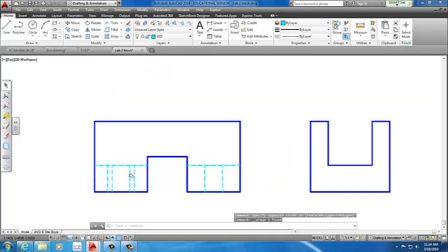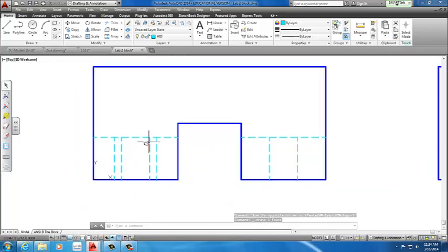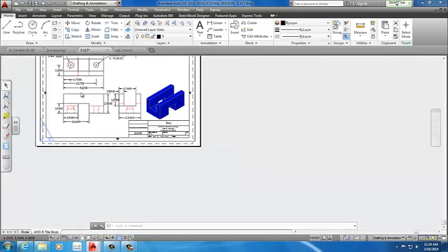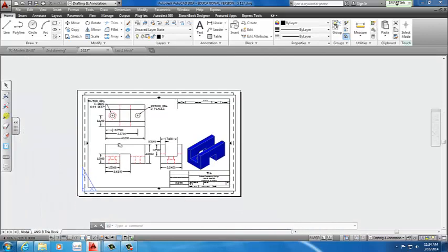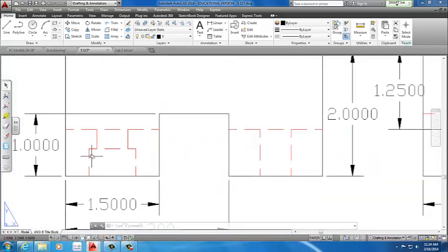Sweep takes an object and you sweep it through a path. The thing about this part is we need our circle, our path is this polygon. So again, to show the actual depth of the modeling, one hole is only 0.44. You can type it in, but that's a lot of work. This is the regular diameter hole. So we do the sweep command.